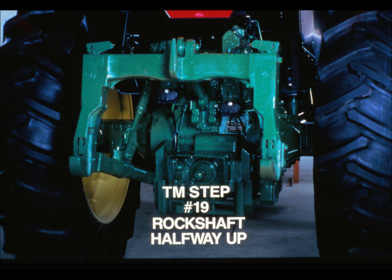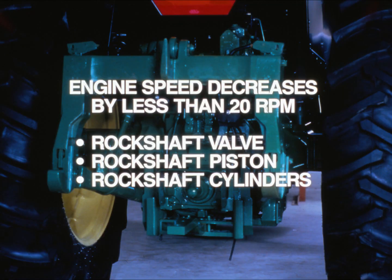Run the engine at 1,000 RPM and record engine speed before and after destroking the main pump. If engine speed decreases by less than 20 RPM, you have isolated the problem. The diagnostic procedure tells you that the rock shaft valve is too tight, the rock shaft piston packing is leaking, or the rock shaft cylinder is scored.